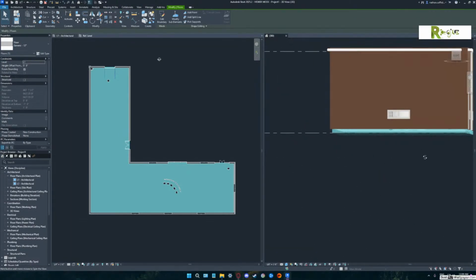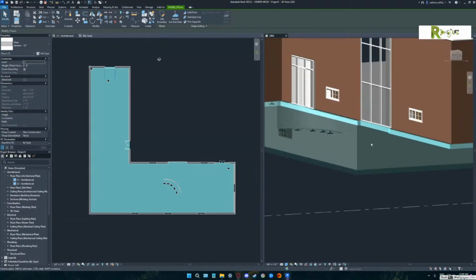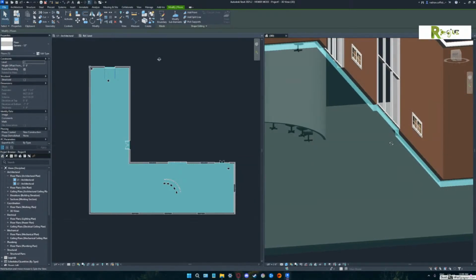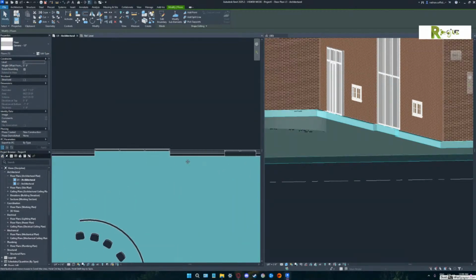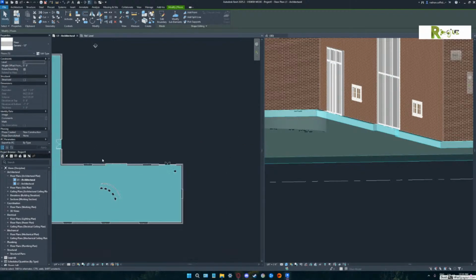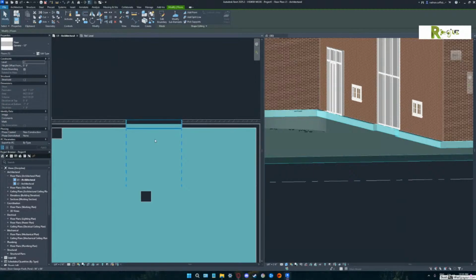You see how it even does the punch out where the curtain wall is? It kind of knows what you're trying to do construction wise. If you zoom into it on plan, you'll see that it put it out to the outside face. Go up to the other corner at the top, because it looks like it was doing it better up there. You see how that blue is going into the window? I think the floor itself actually runs that whole distance out to the substrate, because then the substrate will run past the floor. Okay.